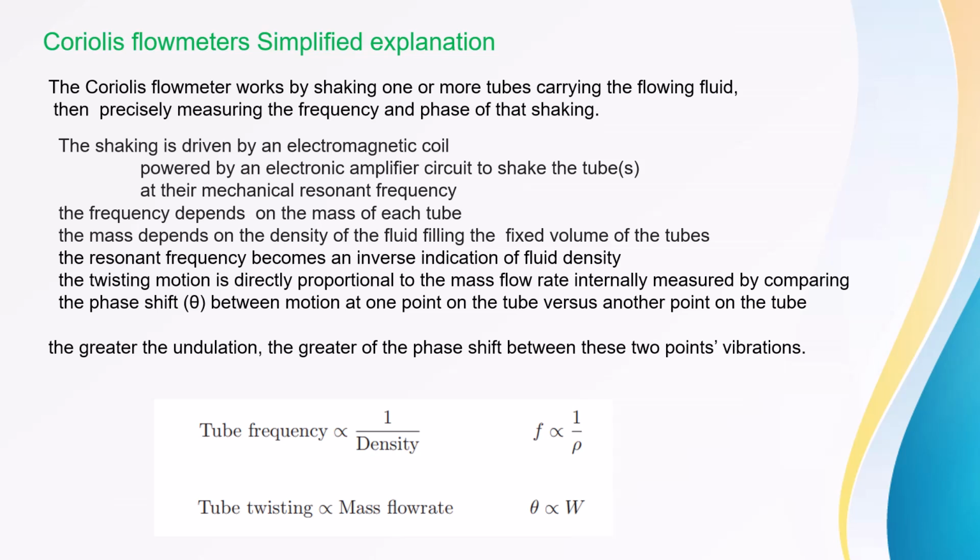The frequency depends on the mass of each tube, and the mass depends on the density of the fluid filling the fixed volume of the tube.